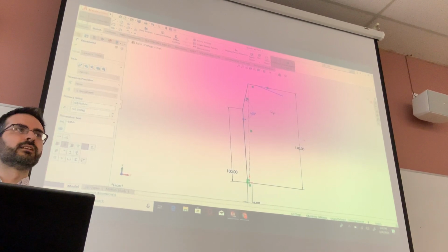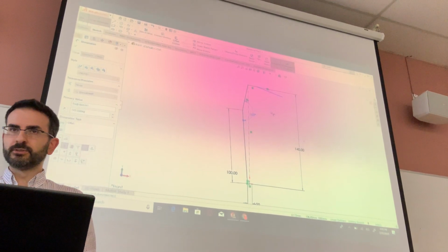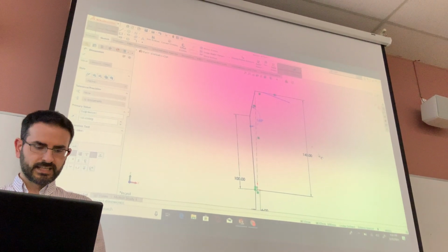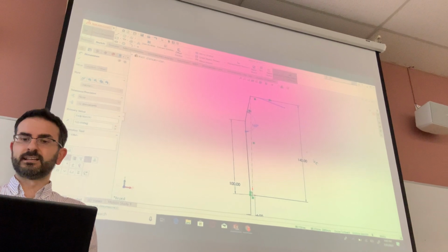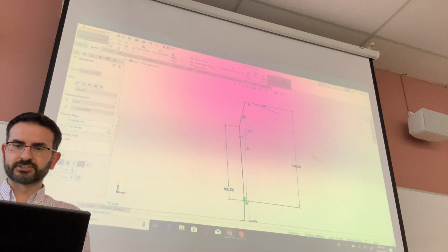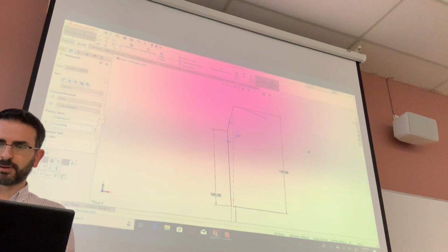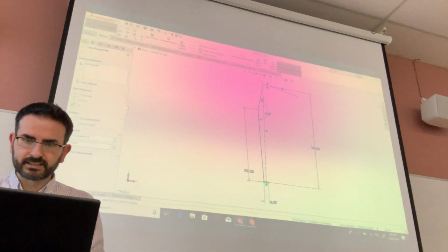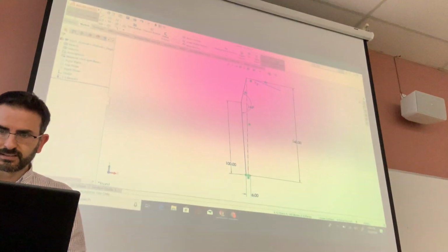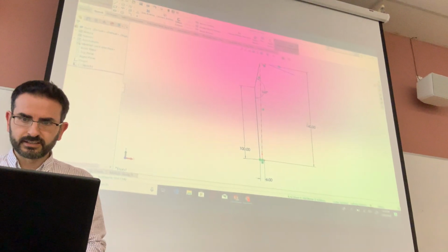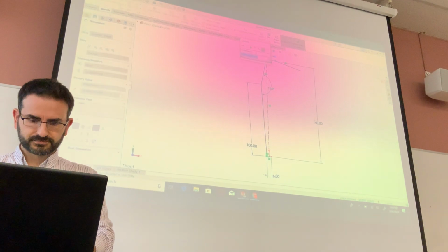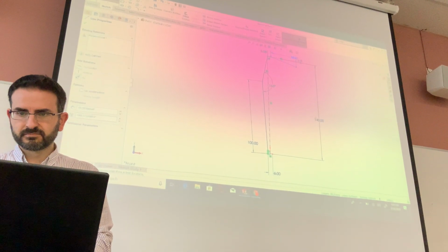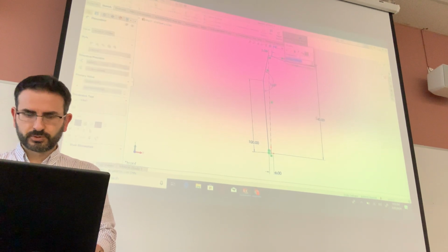If you want to pan around, you can use the middle button of your mouse, the one with the click wheel, with the Control button down. Instead of rotating, it will drag, like it's panning around. That could be useful. Now this little segment here, you go to Smart Dimension and make it 5. This one here, you make it 27.